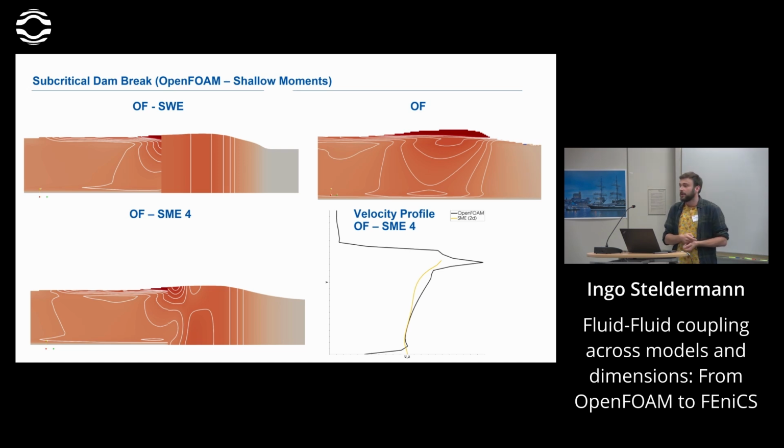Why is that? Because you need to find the right model here that does the right thing with the momentum that you get. Do you have the right viscous stresses? Can you build them in? Here we essentially took an inviscid model, so there's no chance that we recover the OpenFOAM solution here. What we need to do in order to do that, my proposition is, we need to have an OpenFOAM model, let's say K epsilon 3D here, and then a reduced order K epsilon model on the other side. This would be, for me, a consistent coupling with which we can hopefully achieve this view on the other side.